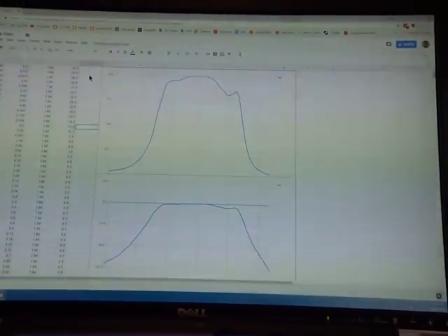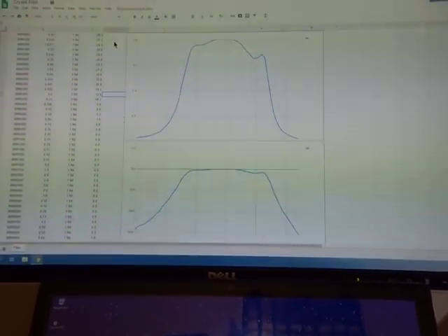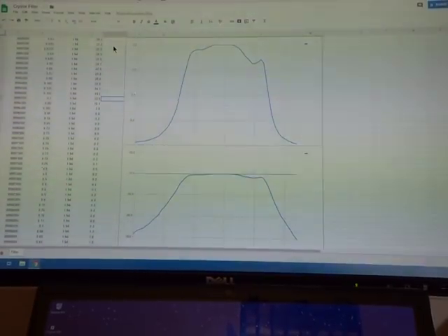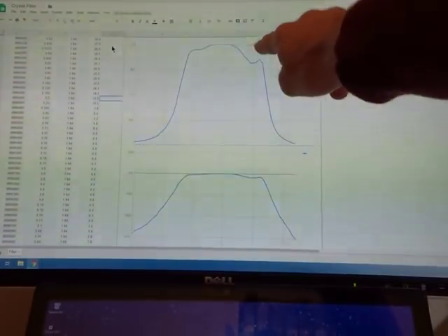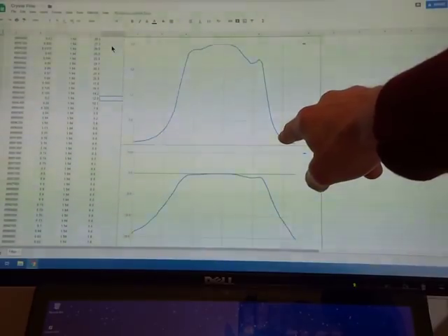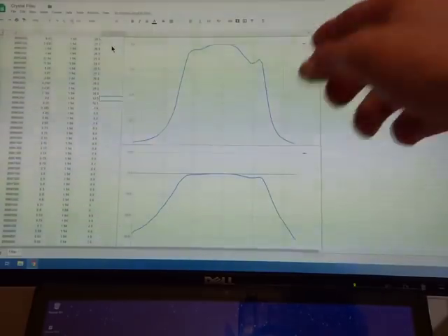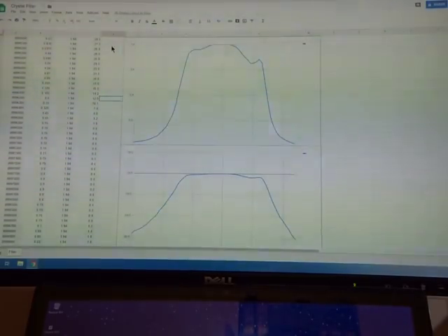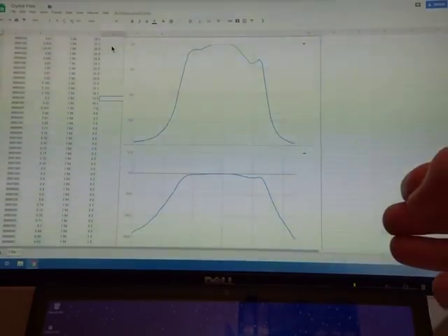It's got a bit of bars coming down from the monitor there. Anyway, there's two plots there. The top plot is just the voltage coming out of the SIG-gen and the voltage across that 51 ohm resistor. So the output of that particular filter at the moment, with that 12 to 6 turns ratio transformer, has sitting on the output side a 51 ohm resistor.